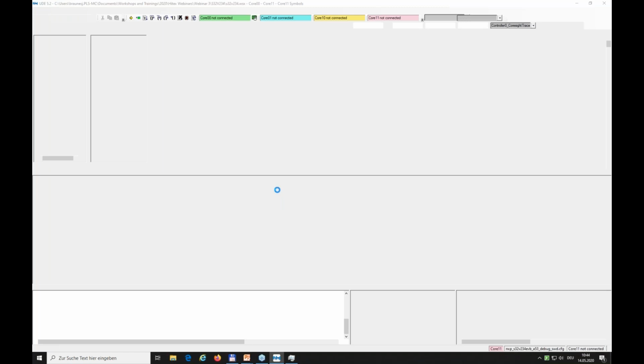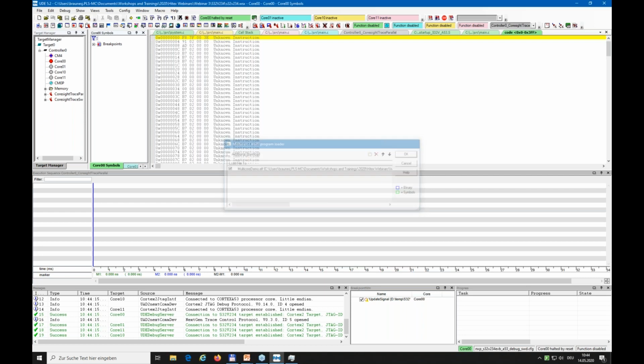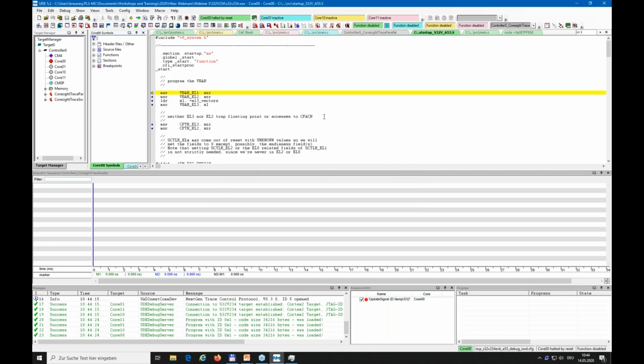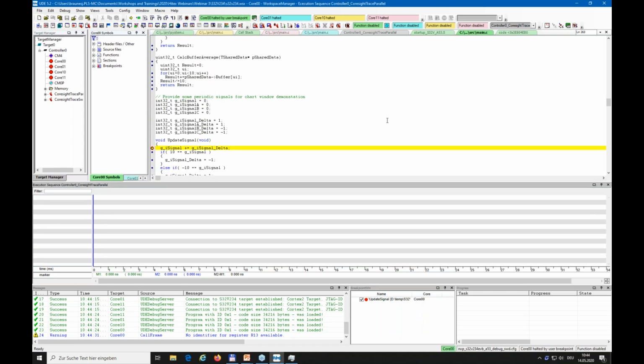And this workspace connects to the UD2 Next in the network. I provide an IP address for that, and we load an application which is quite simple and it's not flashed. It is located in RAM. If I start this application, okay, I hit the breakpoint, and from there I want to start the trace.